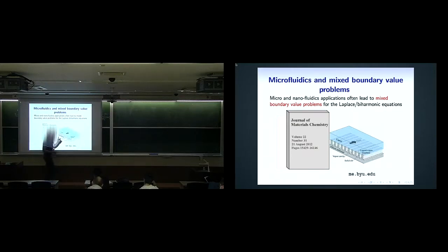Okay? Now, here's the optimization problem. You see, this is a solid surface, a pillar. And so this is a no-slip region. These pillars are made of metal, usually silicon, very good at transferring heat to the liquid. But they're no-slip surfaces. So if the whole thing was no-slip, it would be very, very hard to push the fluid through these tiny chips. You need huge pressure gradients. You understand? So, I want to have these free surfaces here, or these slots. And these are free surfaces.